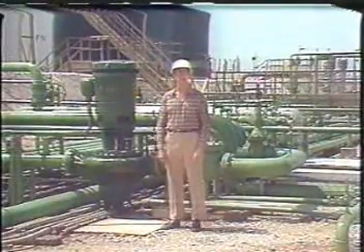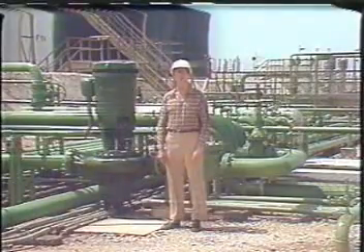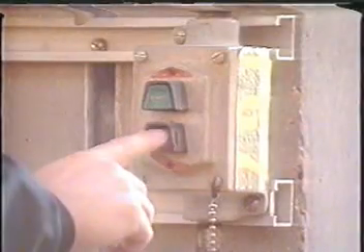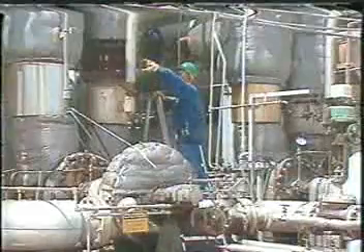Shutdown is basically the opposite of start-up. First, you open the recirculating valve. Next, close the discharge valve slowly until closed completely. Then, stop the motor or turbine.